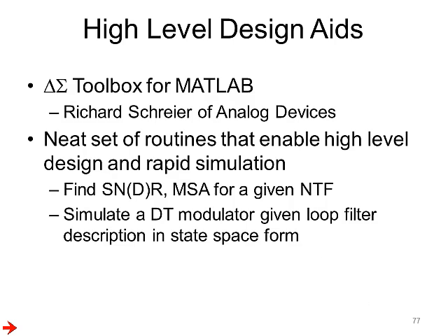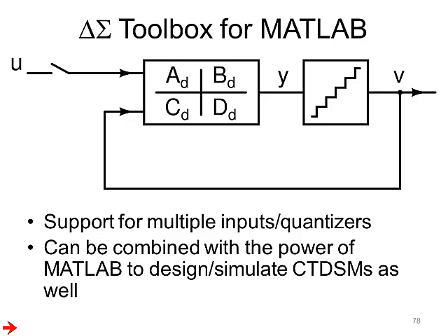Several high-level design aids are available for delta sigma modulator design. Something I really like is the delta sigma toolbox for MATLAB written by Dr. Richard Schreier of Analog Devices. It's a neat set of routines that enable high-level design and rapid simulation. You can find SNDR, maximum stable amplitude, etc. And it's an engine for simulating a discrete time modulator given the loop filter description in state space form.